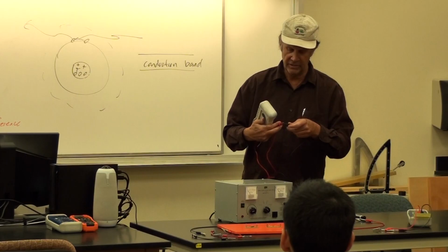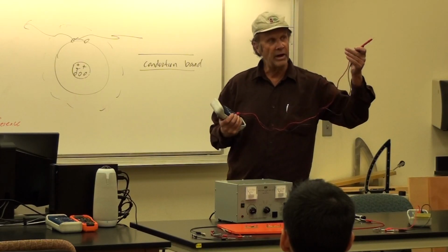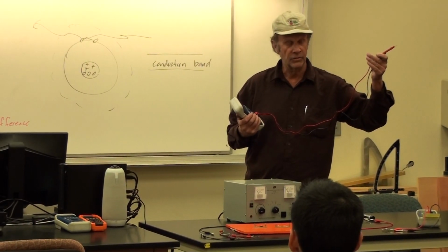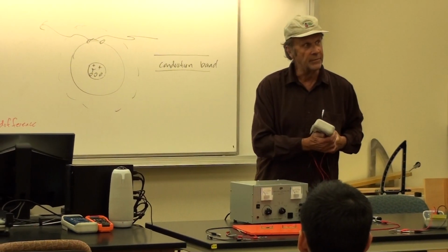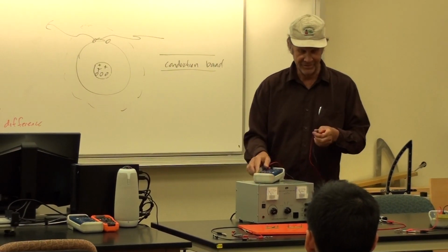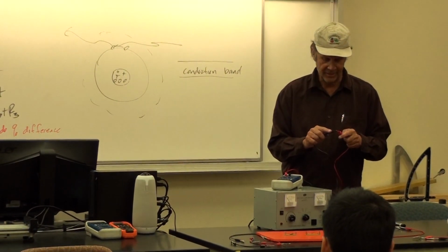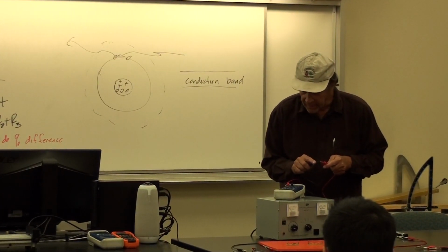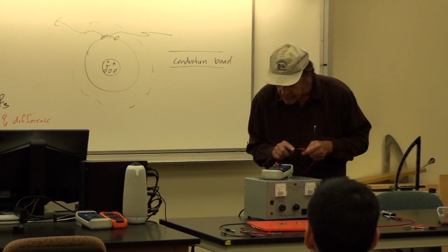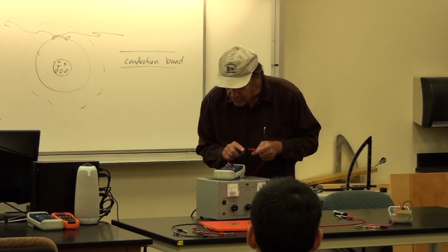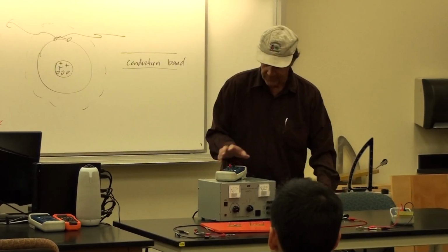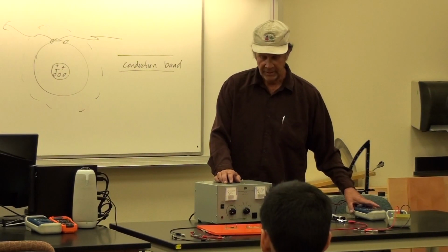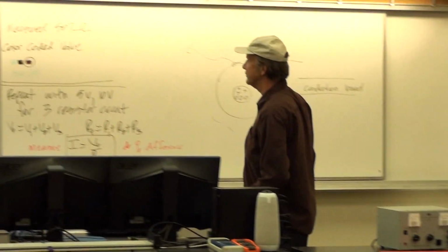If you get 0 when you touch them together, that's good because the wires themselves have resistance, but we want to calibrate those out. So normally that shouldn't show up. You shouldn't have any resistance if you just touch these 2 together. But you'd be getting 0 here. And I'm actually getting 0.1. But that's a possible source of error if you're not getting 0.